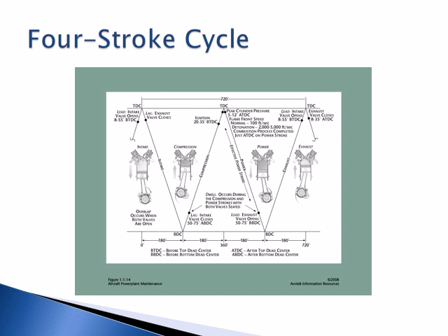Next is the compression stroke, where both valves remain closed and the piston compresses the mixture. Just before top dead center, ignition occurs, typically 20 to 35 degrees before TDC, initiating the power stroke. Combustion drives the piston down, generating mechanical energy.